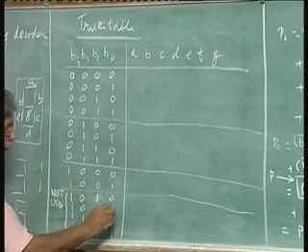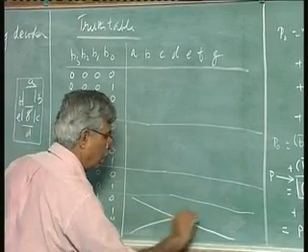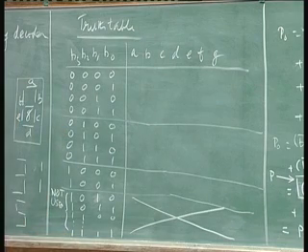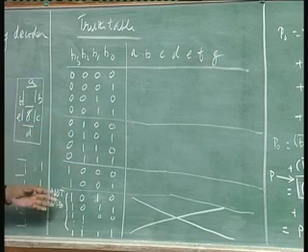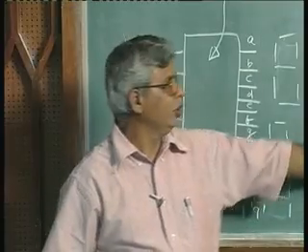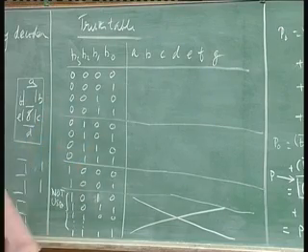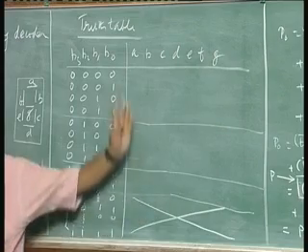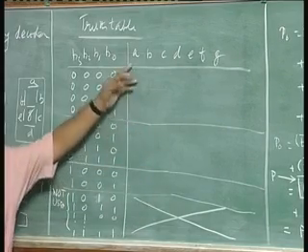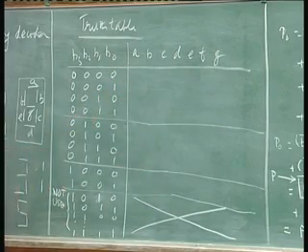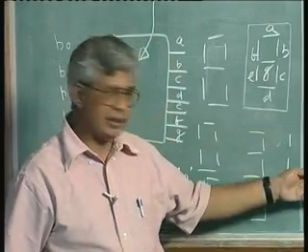So they will have don't cares. I will put a big X. All the columns are don't cares for all of these rows. For the 6 rows, A don't care, B don't care, C don't care. I don't want to go on writing that. So this big X means A, B, C, D, E, F, G are not defined for these last 6 rows.